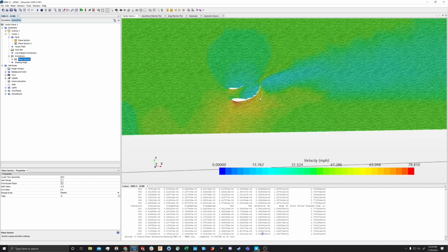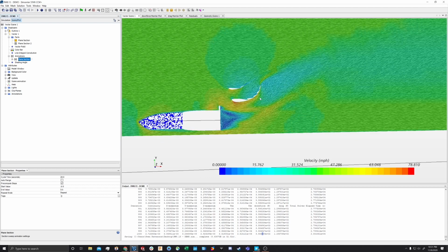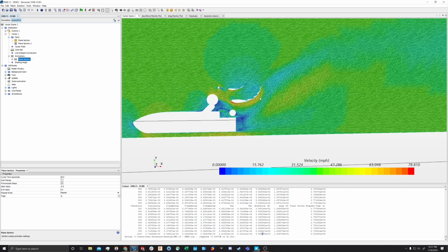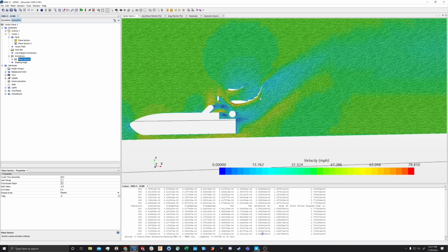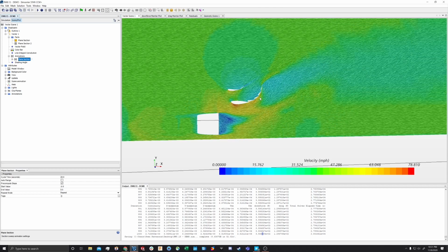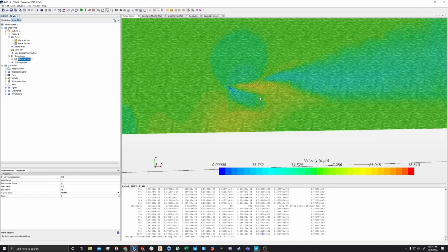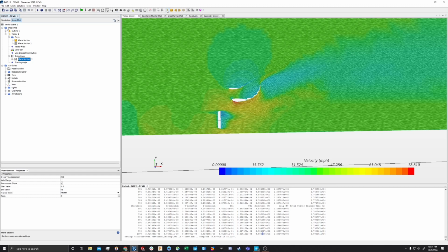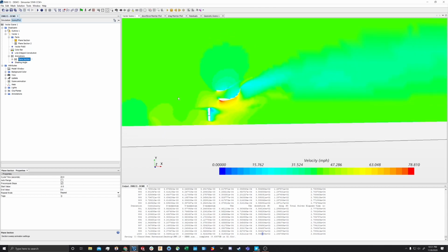And you can actually see the flow over that airfoil in all these different positions. This can be useful, especially for the rear wing and front wing as well, because when they're directly behind or in front of the car, they get different flow, whereas when they're more free stream on the sides, you can see that well represented here. But this is another useful tool just for checking out the flow on the wing in a given direction without having to create a whole bunch of different planes.